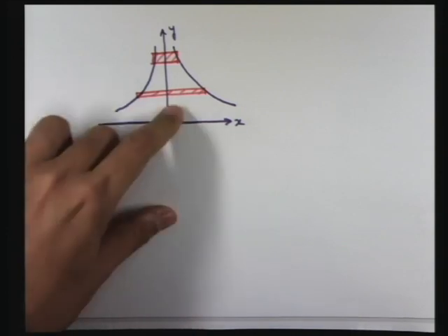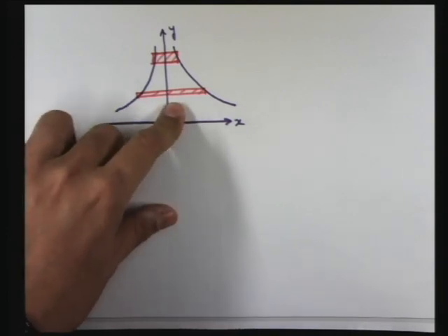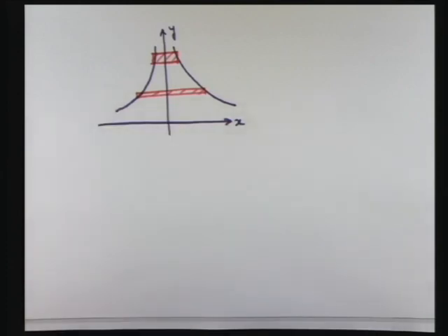You can see, this fluid element is neither rotating nor having angular deformation. It is simply getting stretched along x and compressed along y such that its volume is getting conserved as the flow is taking place along a streamline. The equation of the streamline is xy equal to constant. So this is the physical picture. So this is the kind of flow.